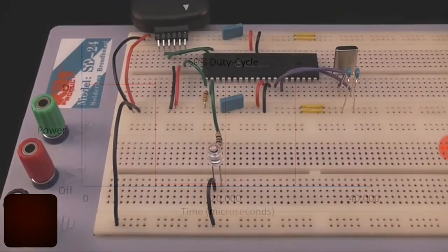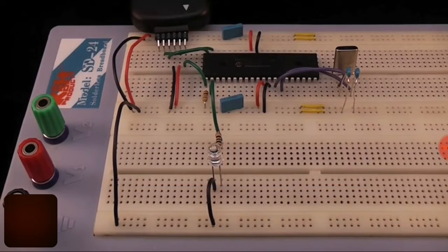When using PWM, it's important to consider how slowly we can flash the LED so the viewer does not see the oscillation. The eye's inability to see rapid oscillations of light is caused by our eye's persistence of vision, which means we see the light is on for a short duration even after it's been turned off. This technique is how televisions display a moving picture, which is actually made up of a number of different still frames displayed one after another.